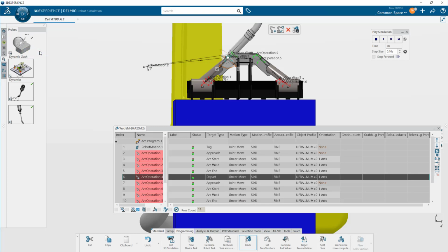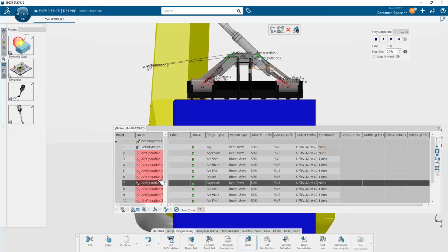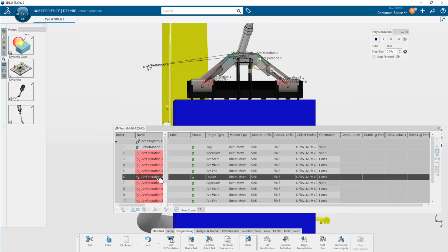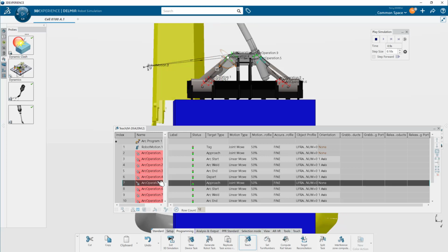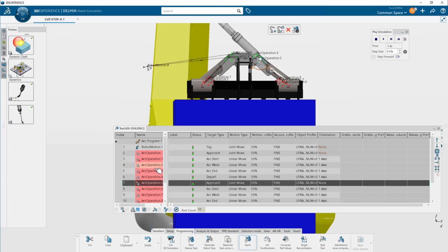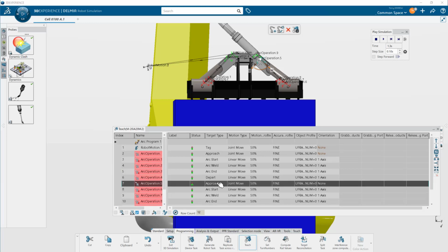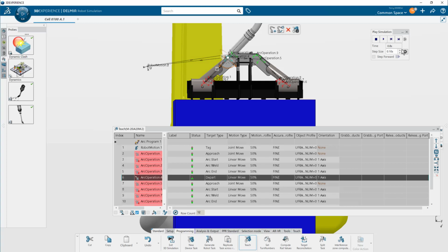Now here's our collision. And I'm going to activate this. And I know it's active because it turns to color instead of being in black and white. So now I have the collisions turned on. This is a dynamic collision, and so then you can see that as the torch moves through that part, there's a collision there. And it was pretty momentary.